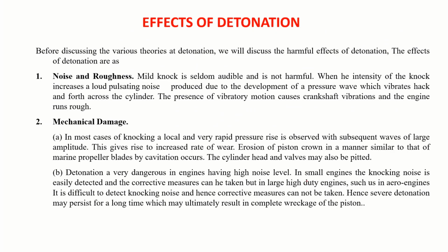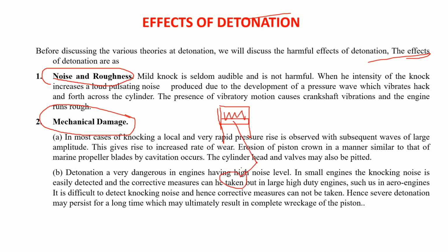Okay. Because of this detonation, sometimes it is called detonation. This makes the engine run noisy and rough, and it will also create mechanical damage. Please know that on the piston, a continuously varying pressure is acting. Because of that, that varying pressure is also acting on the crankshaft. That leads to vibrations.